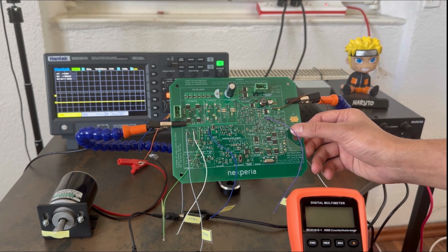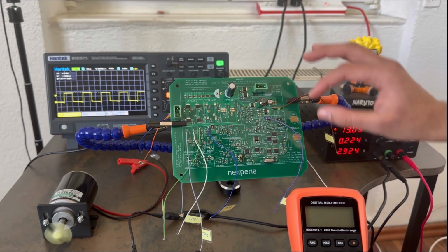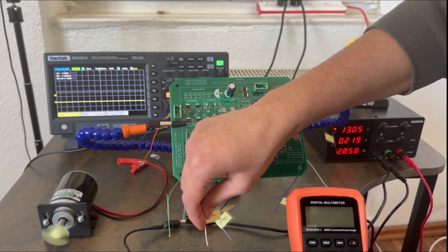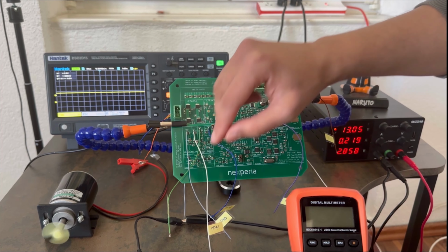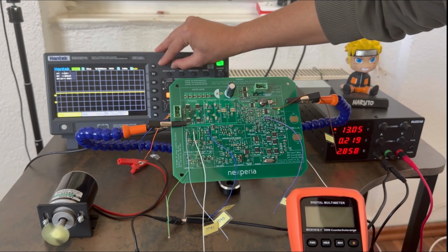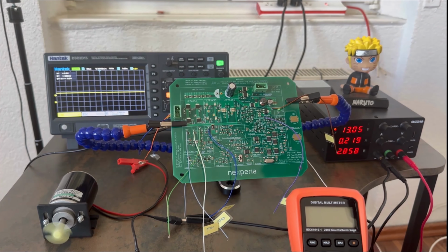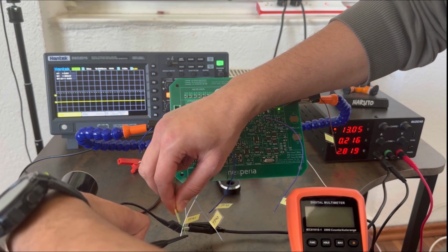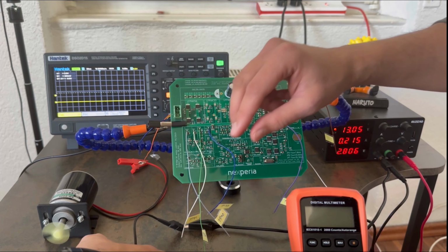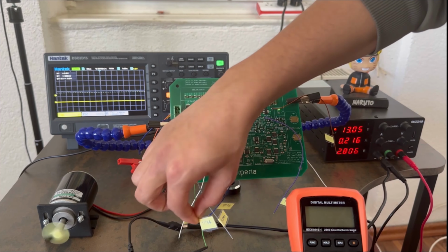Let's see the reverse motor rotation by just flipping the switch. Now we'll see the gate signal of MOSFET Q4 at TP41. It is high. As it is a low side switch, its gate voltage will be low. So the Q4 is on. If Q4 is on, then Q2 must be off. And yes, it is off.